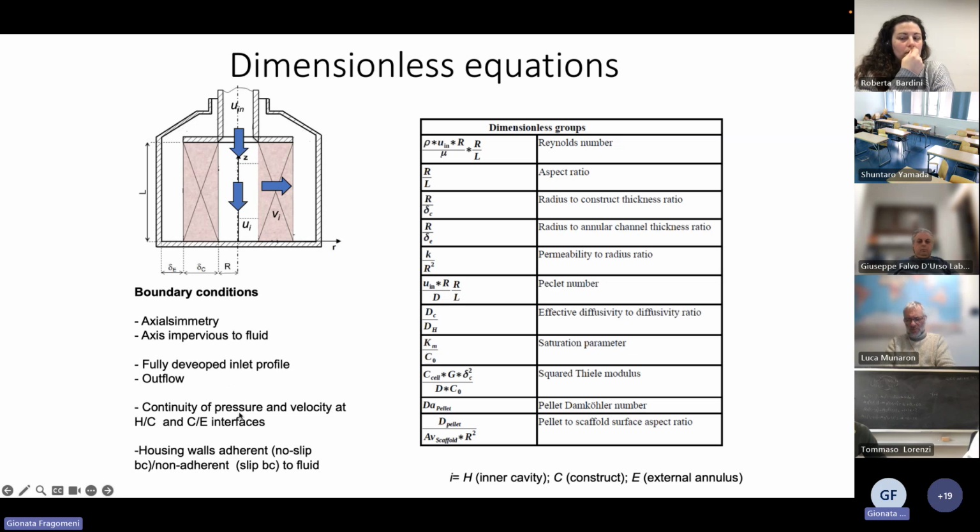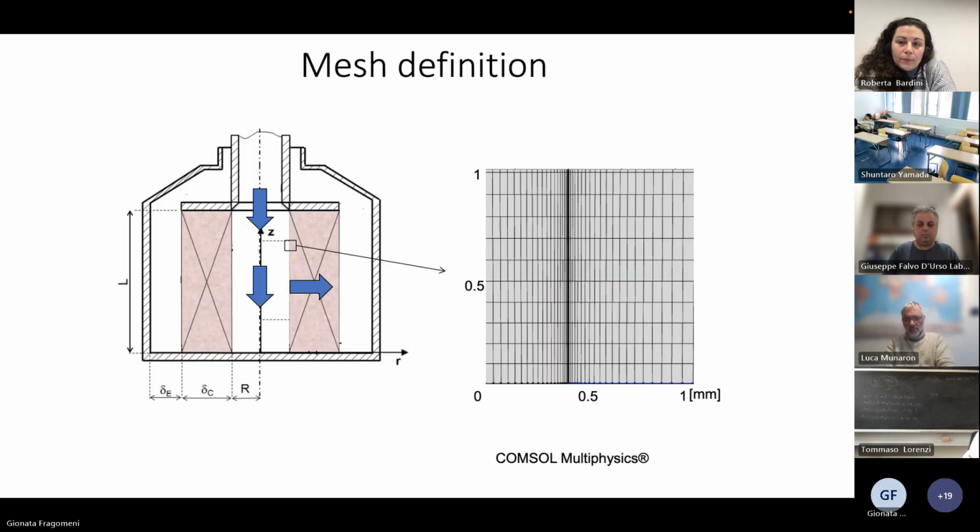There is continuity of pressure and velocity at the interface, and we impose a no-slip, non-adherent condition at the walls.